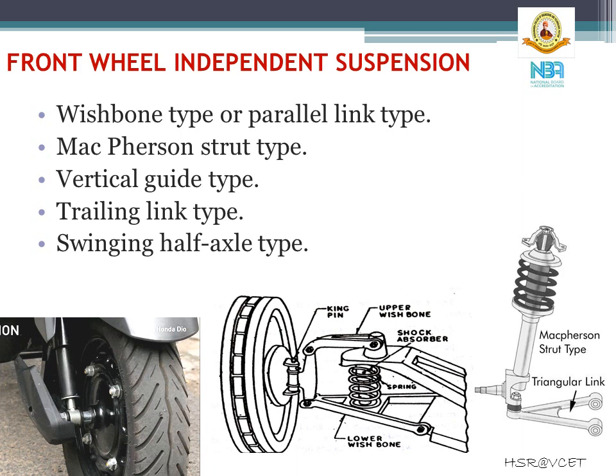Independent suspension. When a vehicle with rigid axle suspension encounters road irregularities, the axle tilts and the wheels no longer remain vertical. This causes the whole of the vehicle to tilt on one side. Such cases are not desirable. Apart from causing the rough ride, it also causes the wheel to wobble. The road adhesion is also decreased.